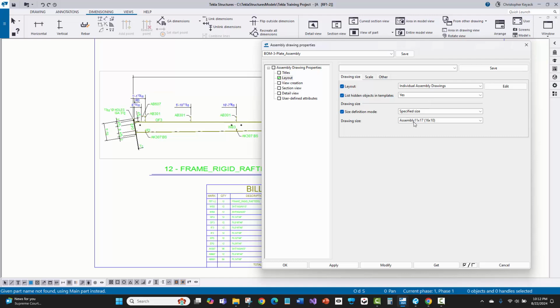And in that particular case, where I did turn the drawing size to a different layout where I'm not using the weld table, that is where I do want to press save on this setting, since the master drawing catalog calls it out, and put that in my firm folder so I don't have to worry about changing that again in the future.